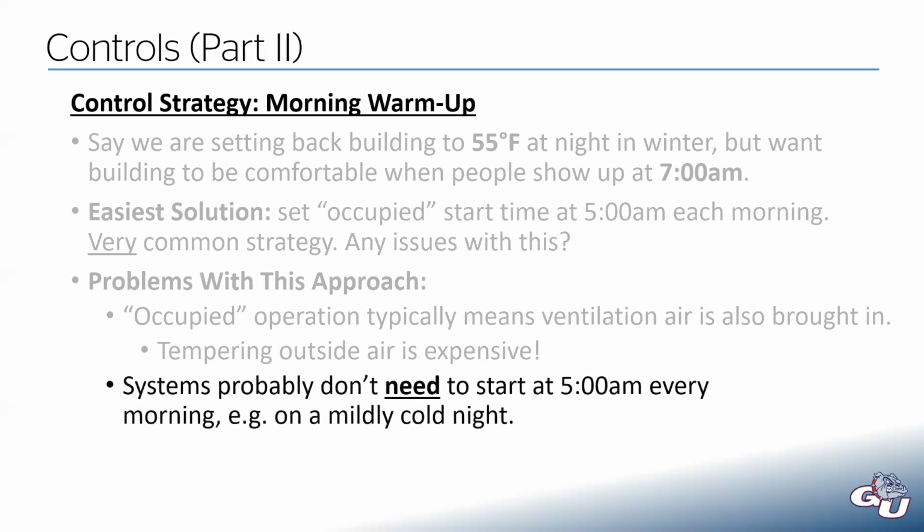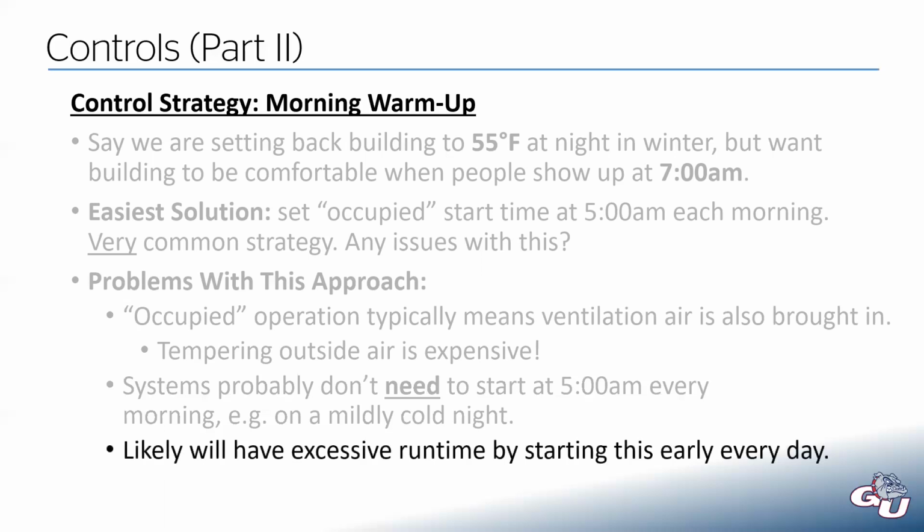We also probably don't need to start our systems at 5 o'clock every morning. If we had a mildly cold night, or if we're in the shoulder seasons where we're in between heating and cooling, we probably don't need to start at 5 o'clock every single morning. And so you're likely going to end up with some excessive run times if you start at 5 o'clock every day.